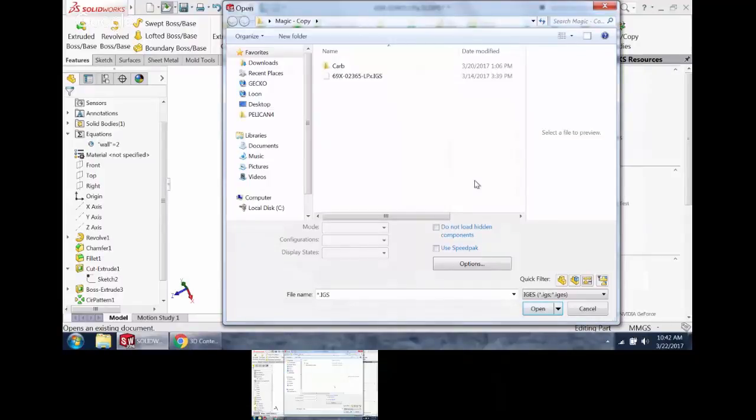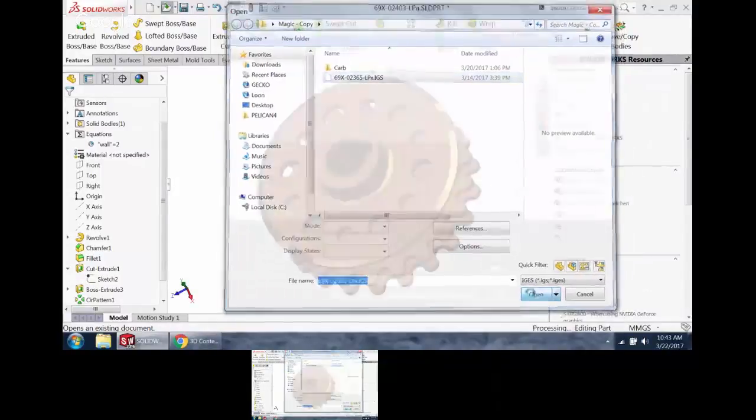The problem with an IGES file is it's a surface-based file. So when you go from a solid modeler, say on IGES, it hollows it out into surfaces. When somebody opens it in SolidWorks, you've got to take those surfaces and make it solid again. There are 3 points where you can have a problem there: either the system it was coming from or SolidWorks. It's got all that work to do. If they send you a STEP file, it's solid from the get-go, so you skip those other intermediate steps. That's better, but let's open an IGES file anyways.